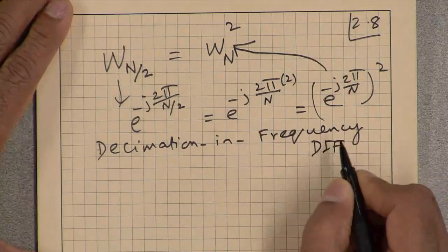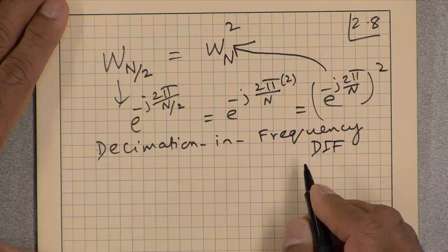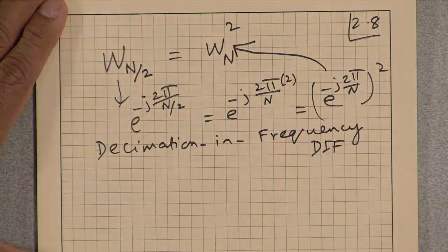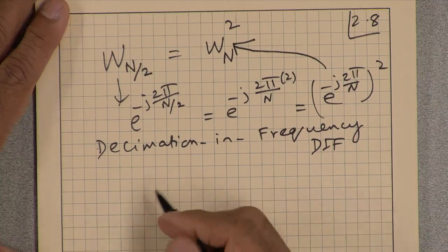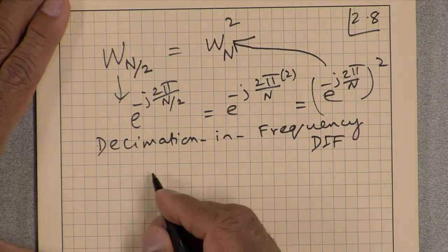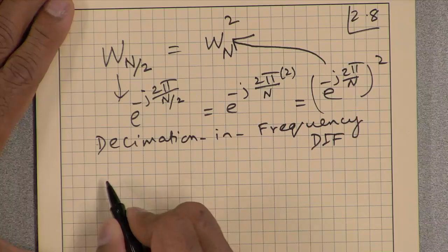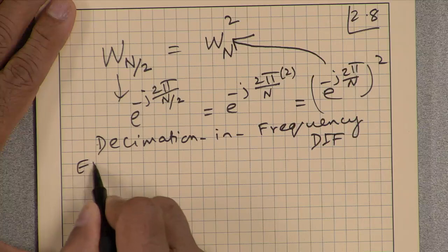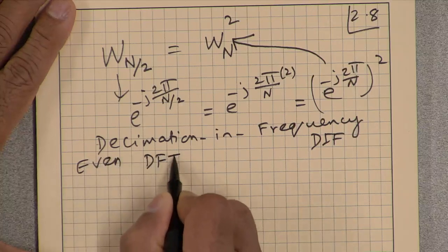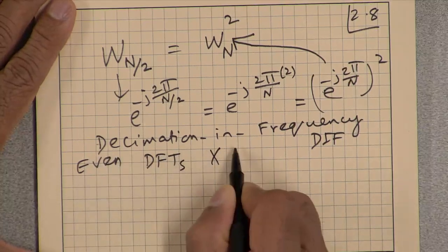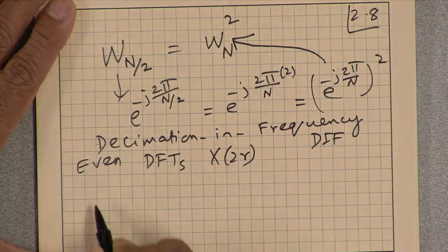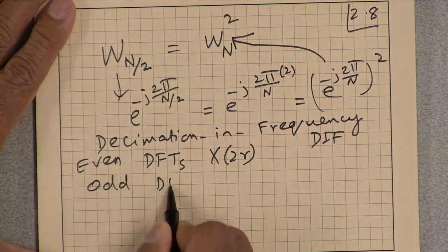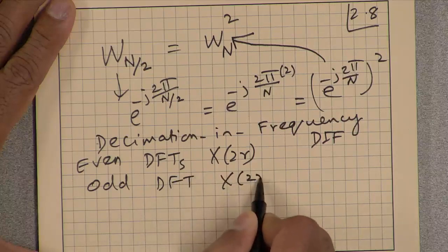The main idea here is, instead of expressing the original sum X[k] in terms of two different sums, here we explicitly compute the even and odd coefficients. So let's start with the even DFT coefficients, and then we will compute the odd DFT coefficients, X[2r+1].